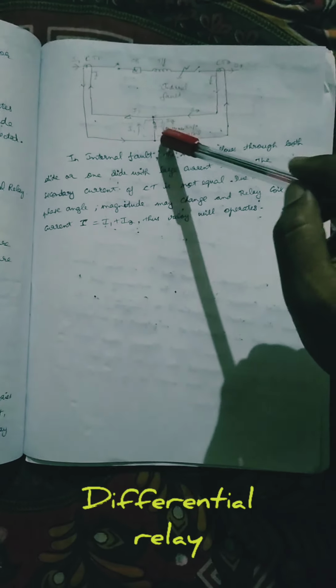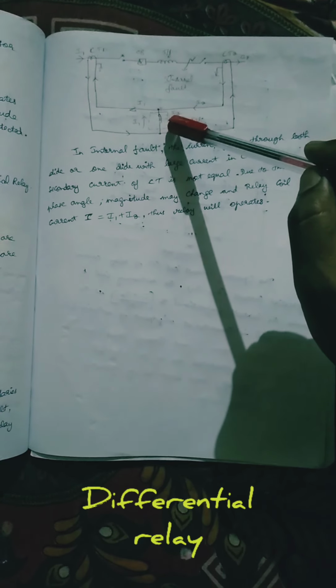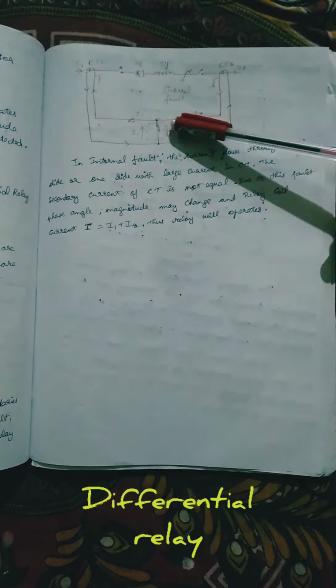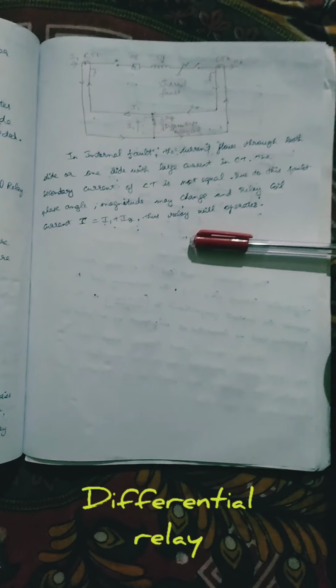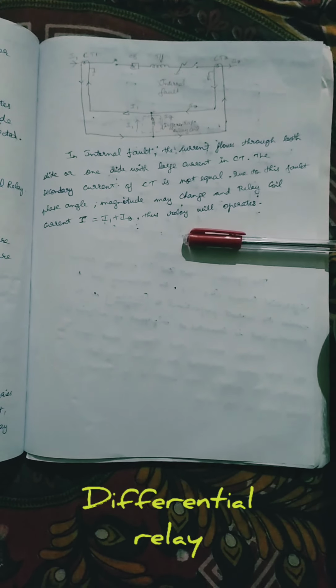In this condition both I1 and I2 get added, and the operating coil current exceeds the predefined value of alarm or trip. In this way the differential relay acts and gives the alarm and tripping signal to the breaker, and the breaker trips.